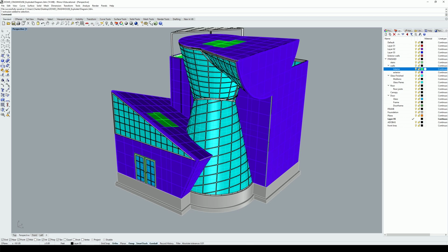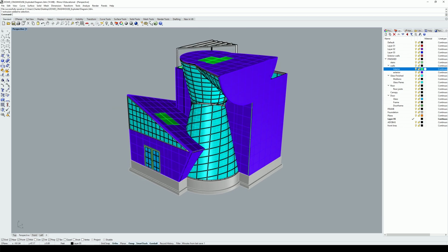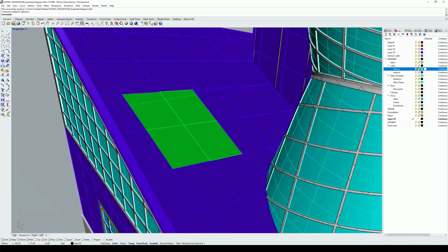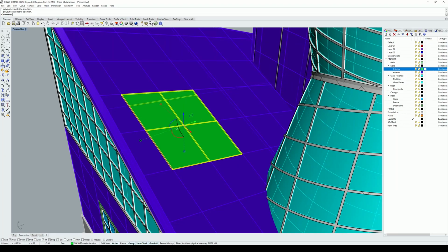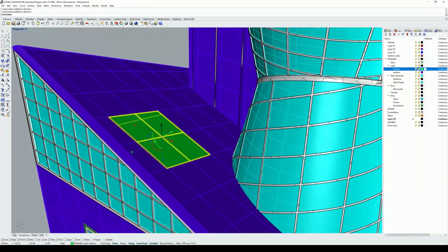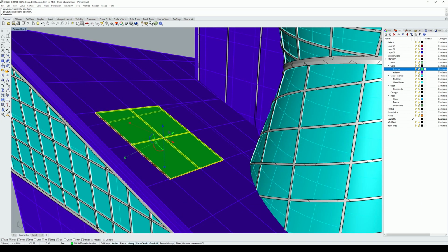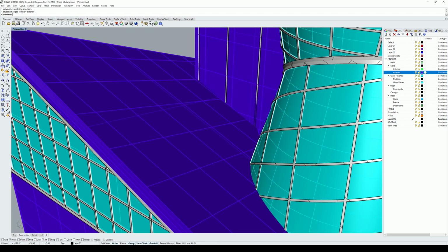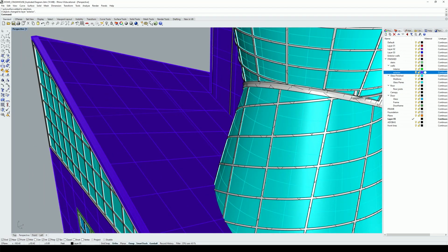So now I'll give you a moment to go through and change this. To change an object, if it's not on the right layer, I can select the objects, holding Shift and clicking. This allows me to select multiple objects. I know I don't want them on this green layer, which is the interior walls layer. I want them to actually be on the exterior layer. So I can go over to my exterior wall layer, right click on the layer, and say Change Object Layer. You'll see that the color of the object itself changes from green to blue, corresponding with the layers, green to blue.